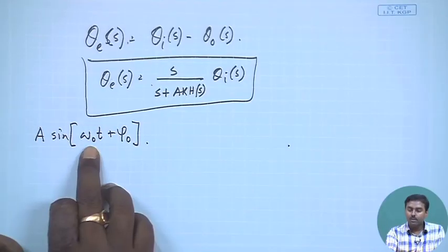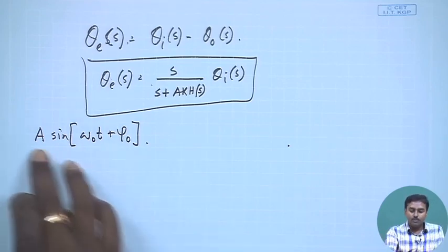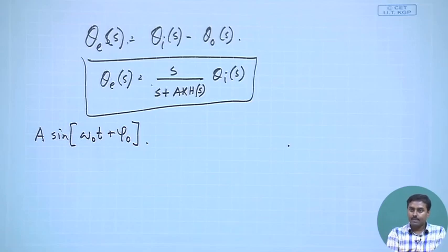So, which we have already discussed, that if we get double sideband suppressed carrier, we actually square it, then do a filtering, whatever frequency we get, we actually make it half, then from 2 omega c we get omega c or whatever it is, that might be a little bit deviated. Okay. So, whatever we do get, we do not say omega c, it is omega 0, let us say. So, we get this, right.